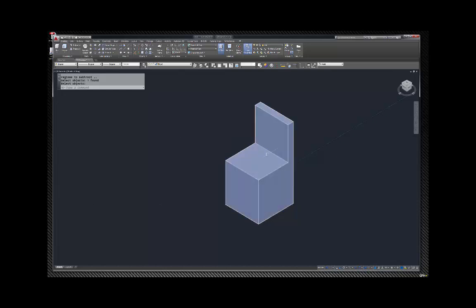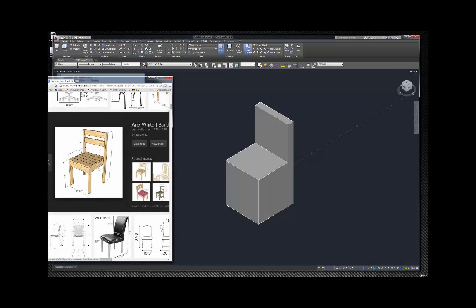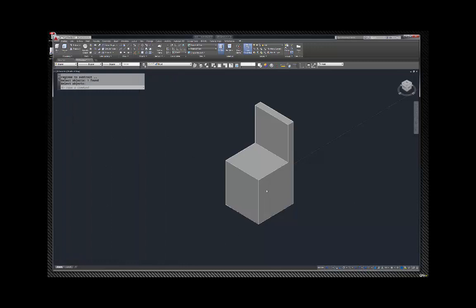So I'm going to look here, and what's the next thing we want to do? How about we'll get this space through here, okay? And what I'm going to do there is come around here and go to my box, pick a point, and go L for length. It says it's 12.5 wide total, so minus 1.5 inches, 3/4 of an inch on each side. So I'm going to make that a total of 11.